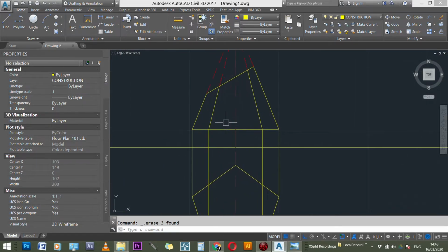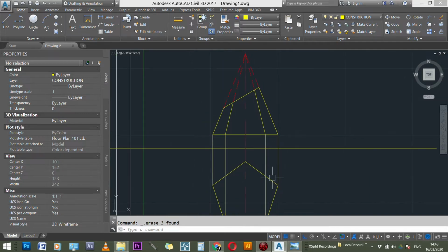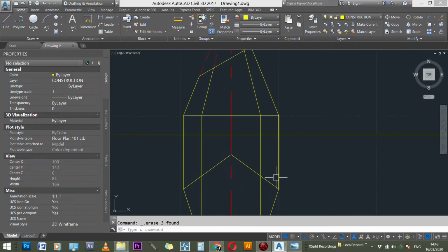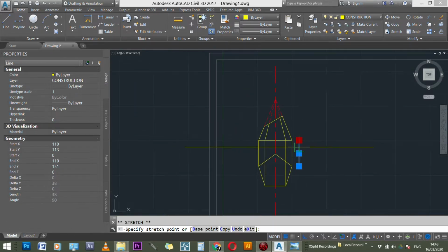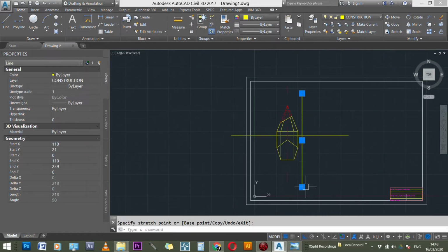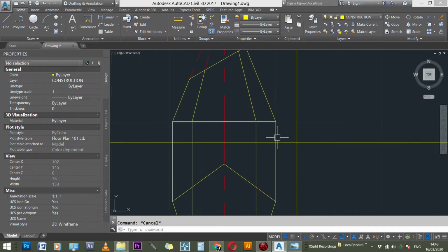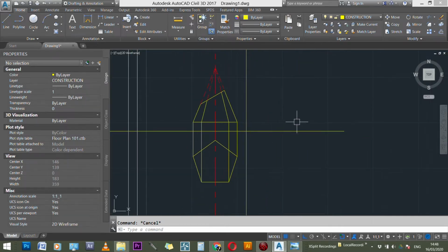Like what we did before, I'm going to offset my distance from my furthest point 10 millimeters to create my frame line. And this is what I mean by my frame line. This frames the drawings, right? This gives us an idea that we have finished one drawing and that these drawings are within a frame.